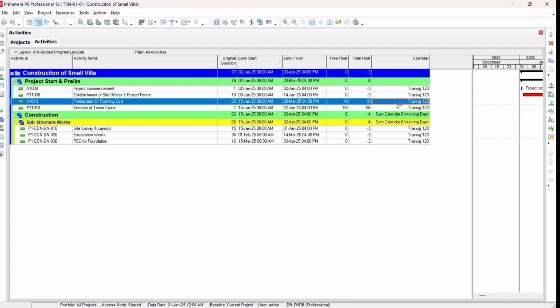Defining of the calendar is very important in Primavera P6, because it will give you the holidays and working hours. Based on this, you can define, design or plan your project. Otherwise, if you do not consider these holidays and reduced working hours, it will unnecessarily show delays in your project, and the client consultant will object or comment on why there is a delay.